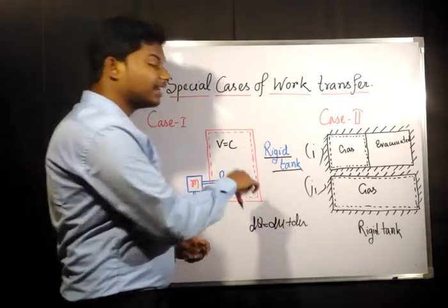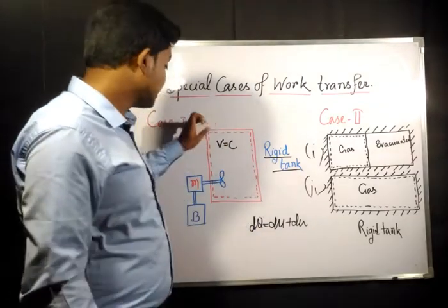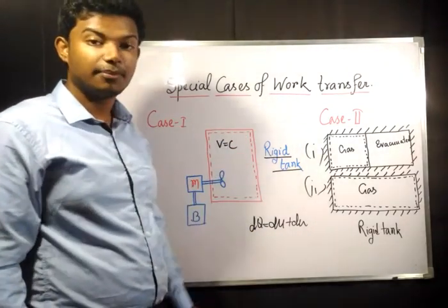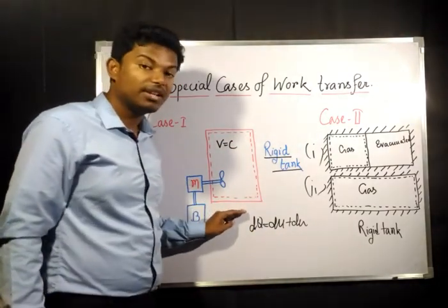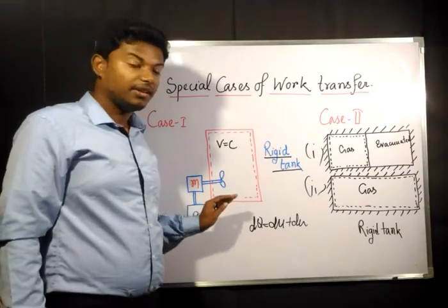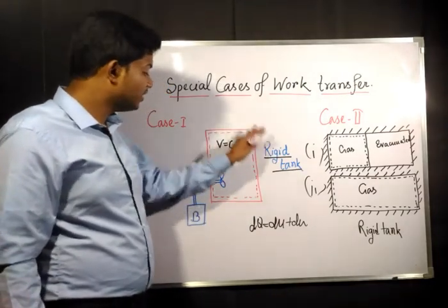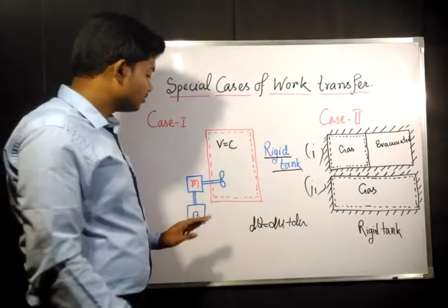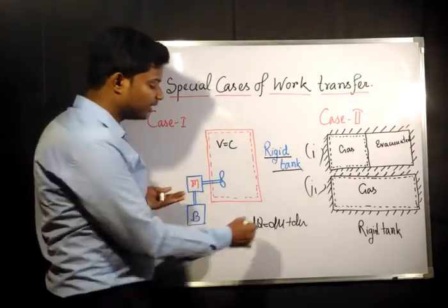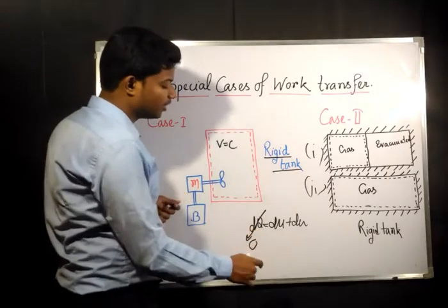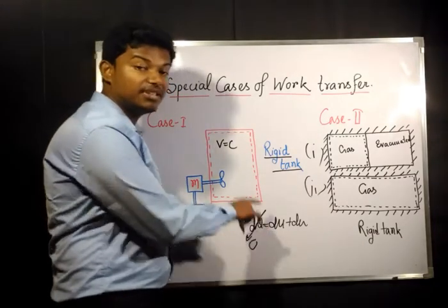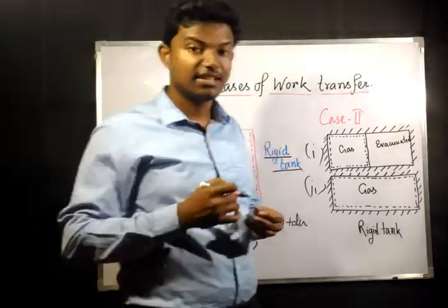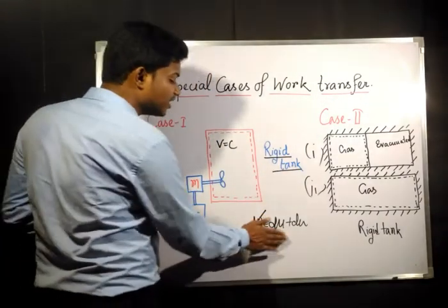Now this tank is completely insulated, and further you are not giving any heat also. Even if you are not giving any heat, the tank is already completely insulated. Since the heat is completely 0, and the temperature is rising, that means there is some change in internal energy. There is always some change in internal energy.